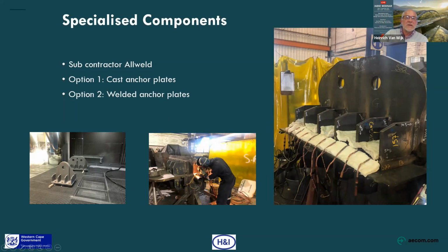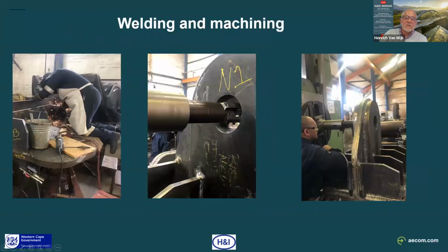and eventually, after some experimentation and so forth, we concluded that compound welded plate anchors were the most suited for our conditions and availability of materials, and with the various plates and welds, we achieved a significant amount of redundancy in the component. This is just some views with class EXC4, execution class 4 quality control, which basically meant that every weld was tested and recorded, and the quality records are linked to actual positions for the life of the structure, so that can all be evaluated.